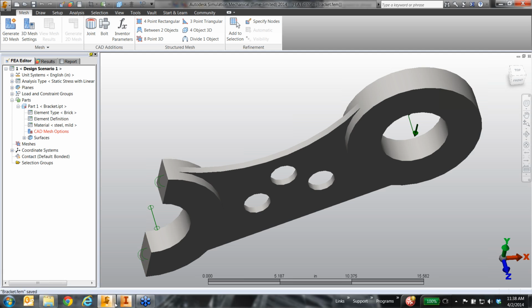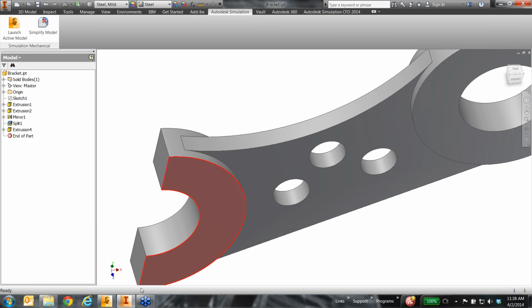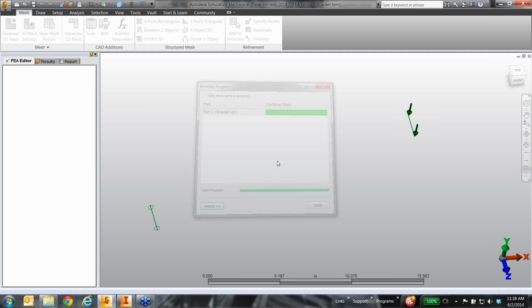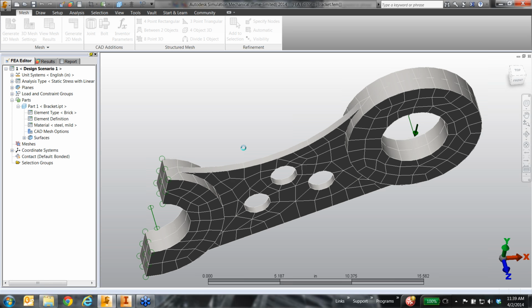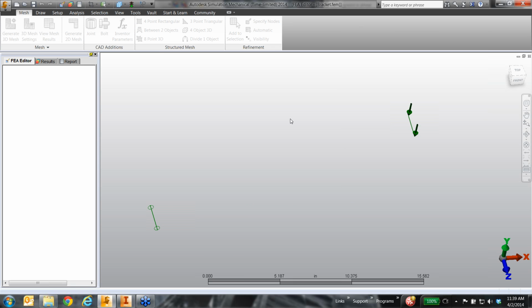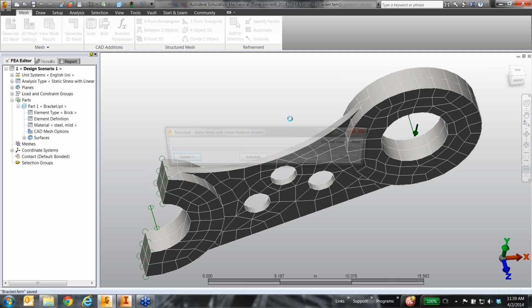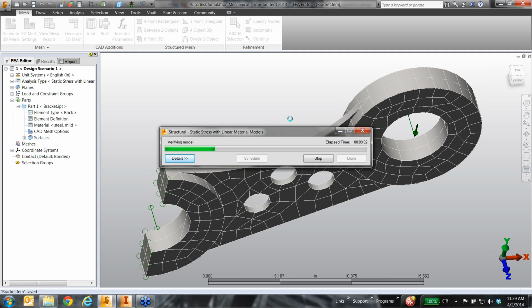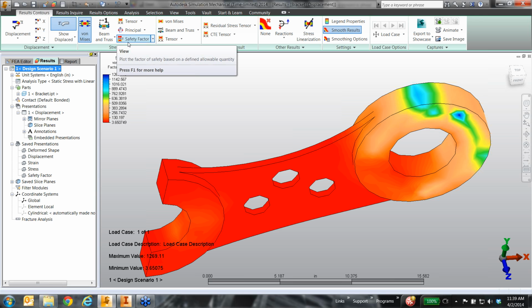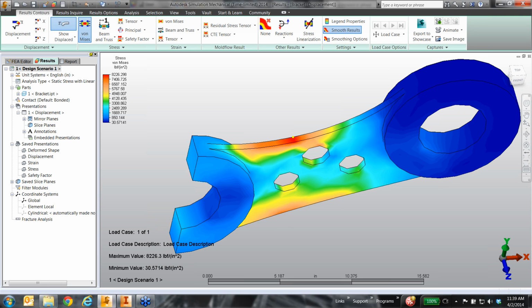So it's changed the geometry inside of here, but if I look back in Inventor, nothing's changed here. It's only on the simulation side. So that way, I'll redo the mesh here. So it keeps constraints, everything. Let's run it one more time here, just a quick test here. So now we see around safety factor of over 3.5 there, so that way 8,200.